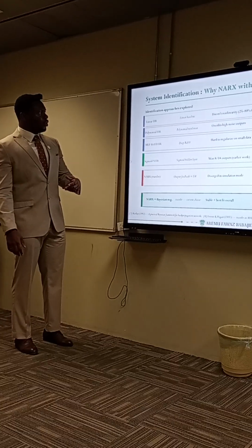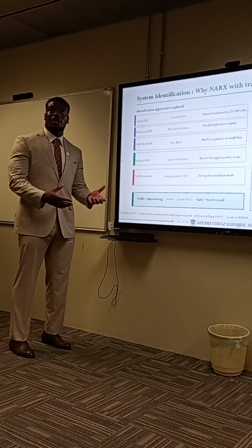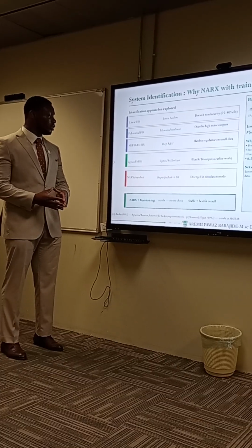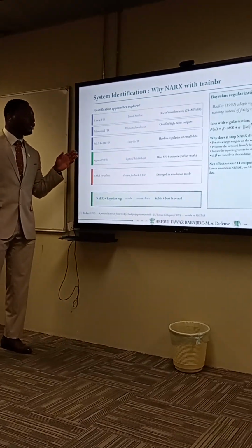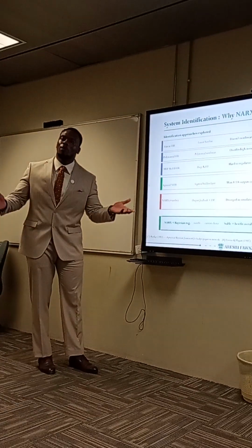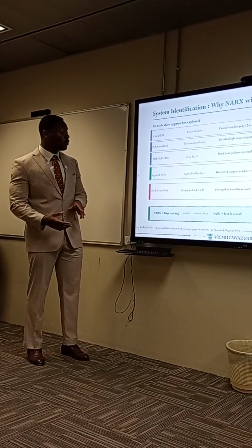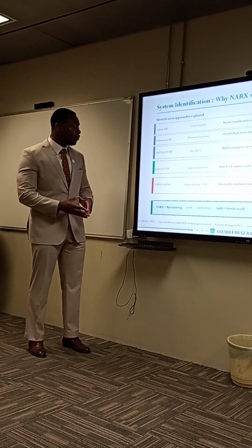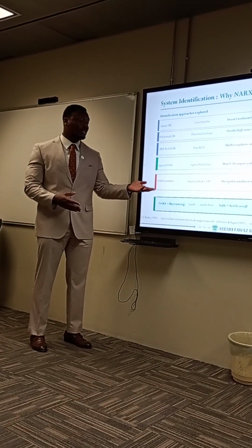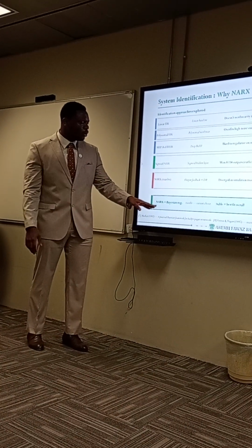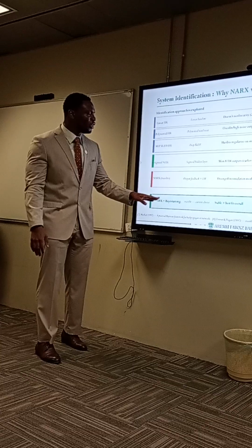So in the end, system identification is another very important thing. Like I said, several other system identification methods were considered, but primarily we were in a pickle between 2 different models: either a sigmoidal nonlinear finite impulse response model, or a nonlinear autoregressive model. For the first, the algorithm was Levenberg-Marquardt, and then we switched to a NARX model, but instead of Levenberg-Marquardt, we used Bayesian regularization.